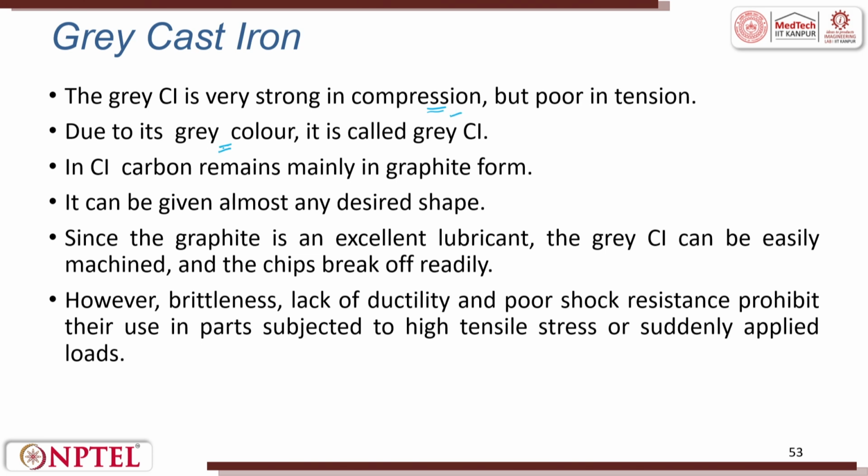It gives you a grey color, that also we have discussed. Graphite is formed instead of carbides. It can be given any desirable shape. The only thing is you should be very careful with the surface to volume ratio. That means the volume of the material should be sufficient as compared to the surface area.